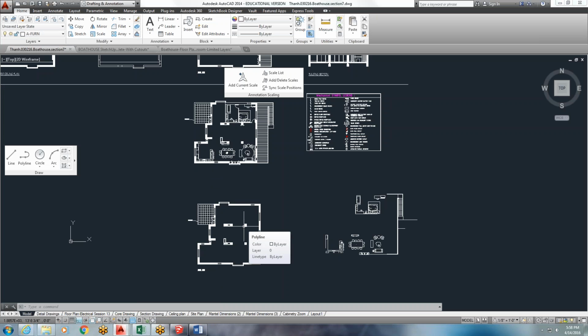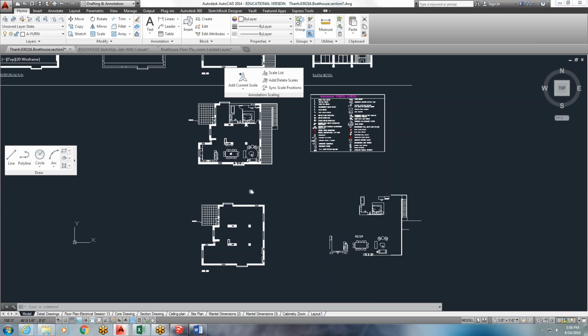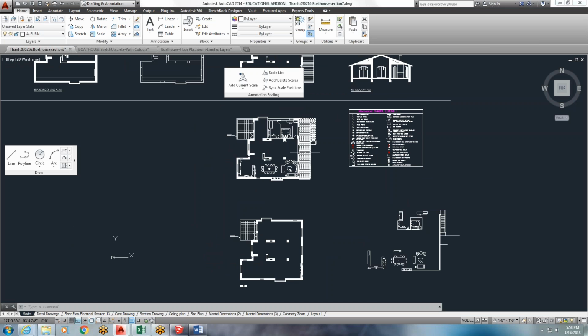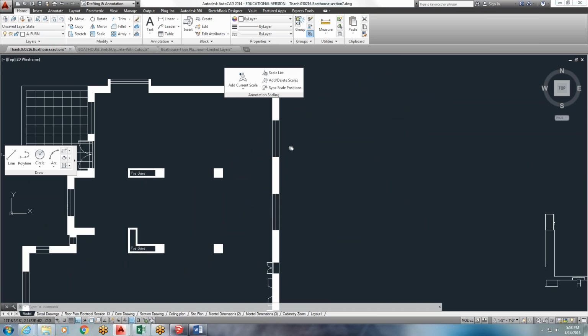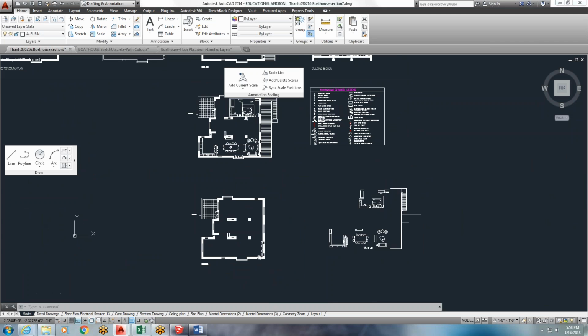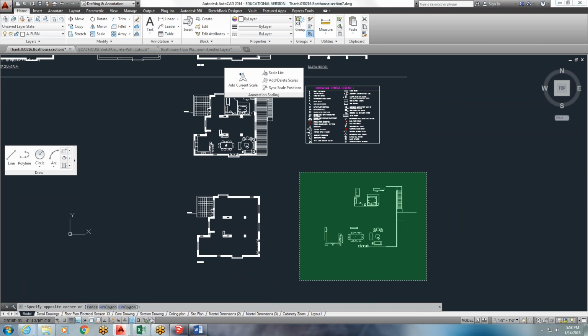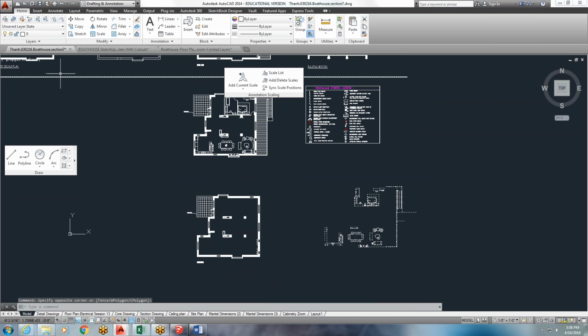And stuff like that happens all the time in the field. We measure wrong, we don't do something right, so I'm just going to treat it that way, but I do want it to look correct in your drawing and in your SketchUp. So that's where you're, from last week, adding the new stair in there. Now we're exporting the new flat version of the stair onto our drawing. So you'll take whatever stair you had when you copy your floor plan down and delete it off, clean to the corners. Okay, then you'll come over and you'll bring this part of your drawing